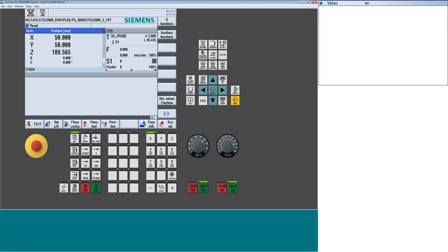If I was to hit the actual machine values, it would say machine, and potentially it could show you this MX1 or MY1. And that's just displaying coordinates relative to the fixed machine coordinate system 0. Every machine has two basic zeros, or let's say a starting 0 first of all. And your starting 0 is the machine 0. That's where every machine is initially referenced from.